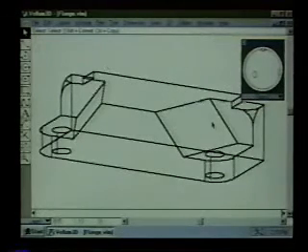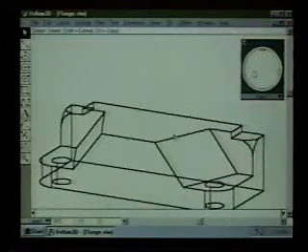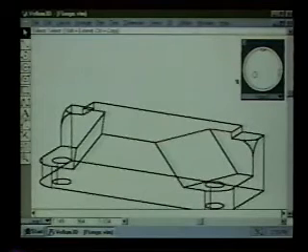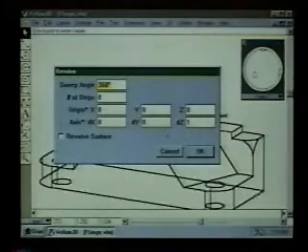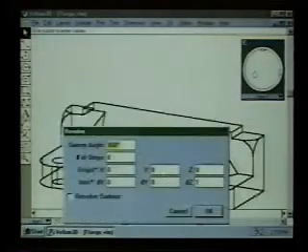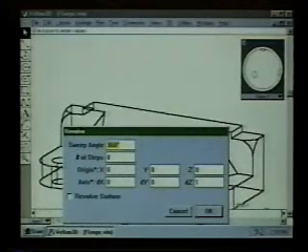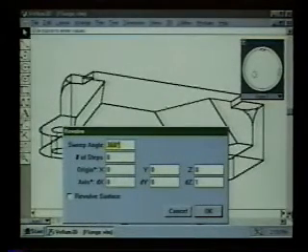Now I'm going to go on and build kind of a domed flange on top of this part, and again there's probably many ways to do that. What I'm going to do is pick this line and this one and this one and use those and sweep them over the top about the center of this part. So I will use the revolve command in this case. Now what do I need to do here? Well, I need to fill some values in here. Clearly the sweep angle ought to be 180 degrees, not 360, and I'm going to use 2 steps instead of 8, and you'll see why.